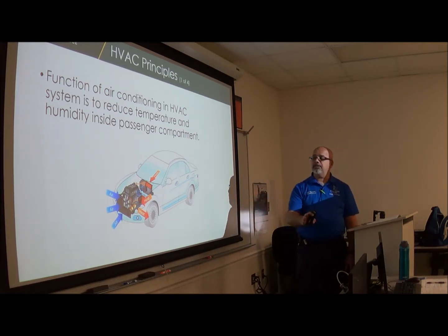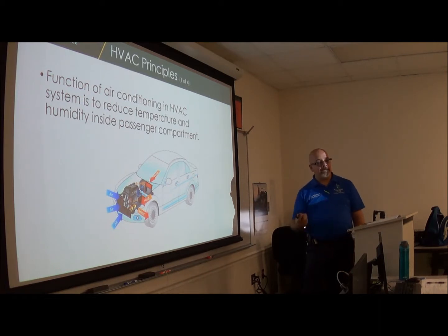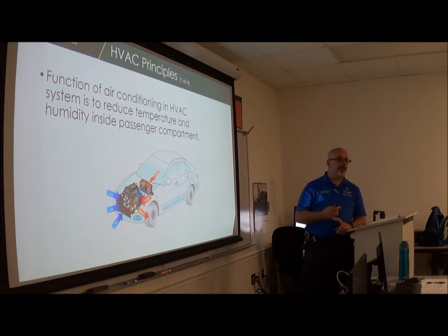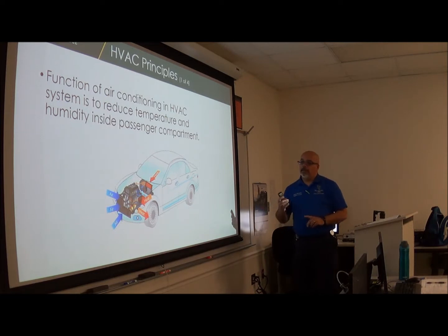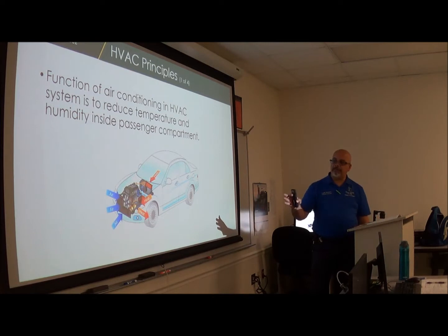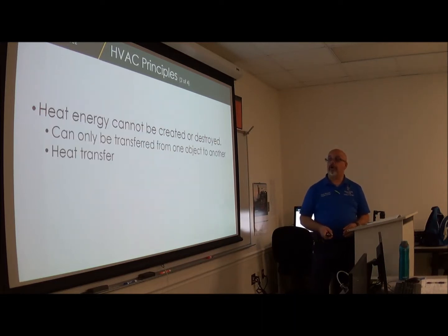That fan is pulling that air in, and besides cooling the evaporator, it's cooling also the radiator. The air that comes in through there will take the heat out of that radiator and that condenser so that it could be cooled down for the air conditioning to work properly.